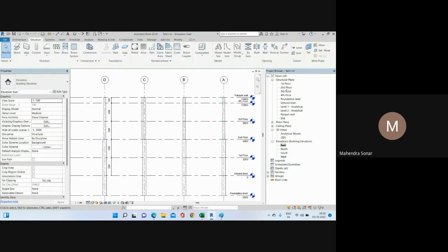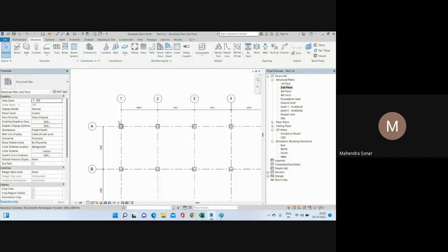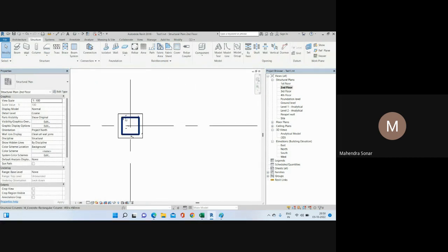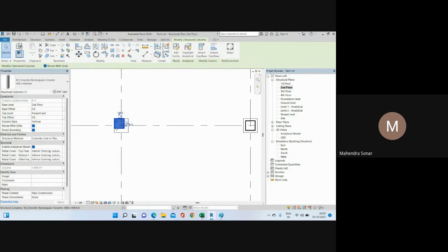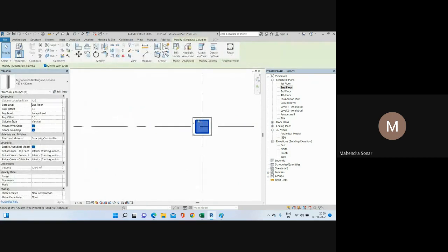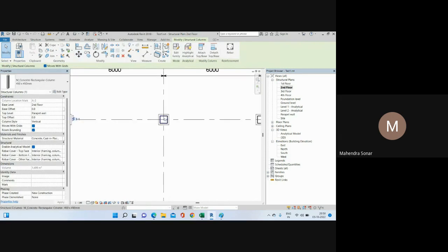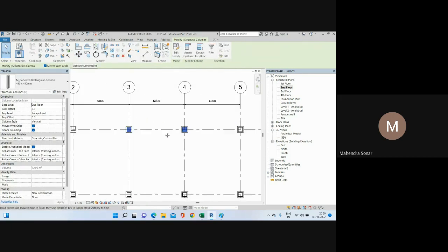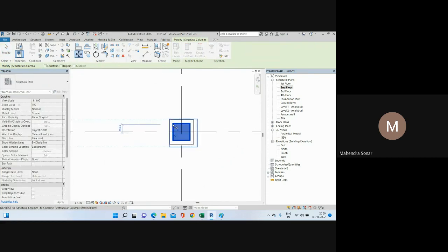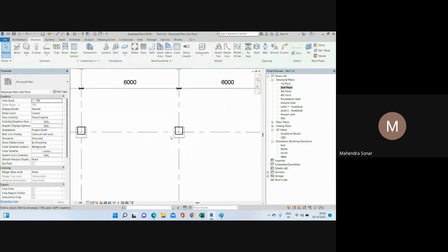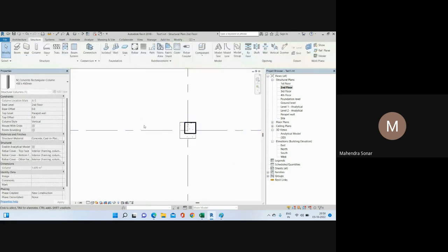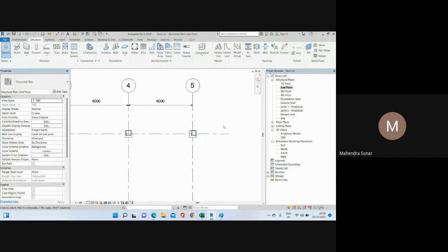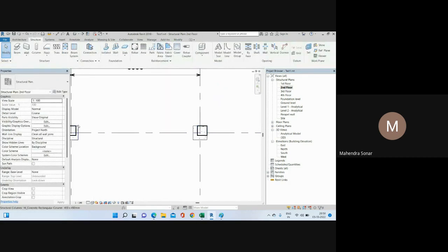Right? So if you go to the second floor, this is your corner column. So you need to align this face. So just use the MV command and move. And on this side, your column should match here. All the periphery columns should be at one level. Means this outer face should be one for both columns. And here this corner should be here because your building finishes here, right? If your building continues, you can give the same criteria for that.